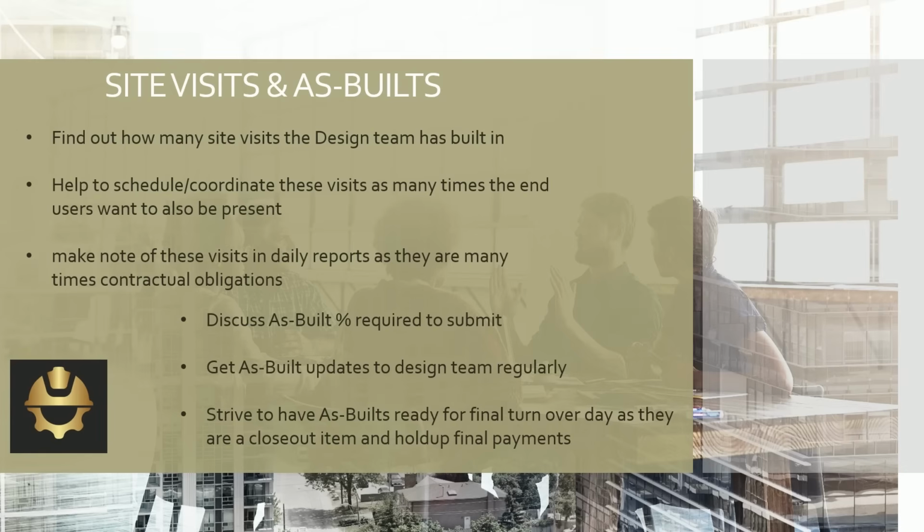You can't wait until 60% and hand them an as-built and think that they're going to have that submittal in time. As-builts are tied to money on a lot of the federal projects, and a lot of times they have somebody that will come to the site trailer monthly and make sure that you're keeping up on them. Sometimes those folks really look and they know what RFI number you're on, and they want to make sure you're current before they release your monthly pay app for the contractor you're working for. Sometimes they're more lenient on that, and when they're more lenient, it's easier for us as QCs to fall behind. But it's really important that you stay up on that and that you get them to them. The design team has to have time to implement the changes to give you the package for the submittal.